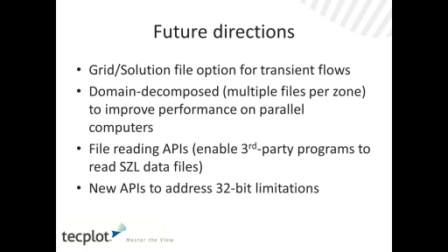It looks like we're getting more questions over here. We have a couple more questions, and then Durrell wants to show something. One of them is, will the SCPLT files help with redraw time? At this point, no, they don't help with redraw time after you rotate, for instance. So if you're rotating and it redraws slowly, it won't help with that.